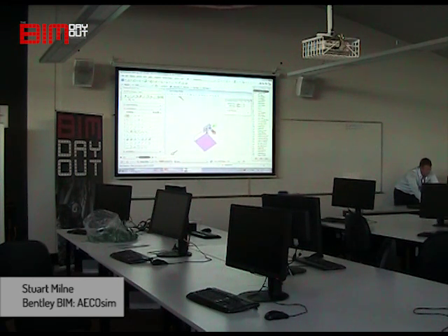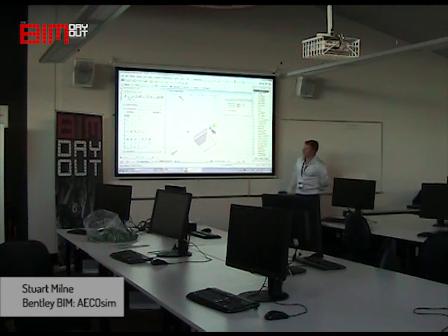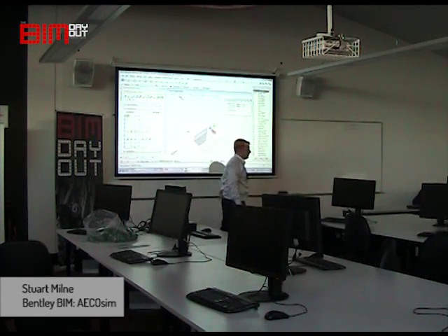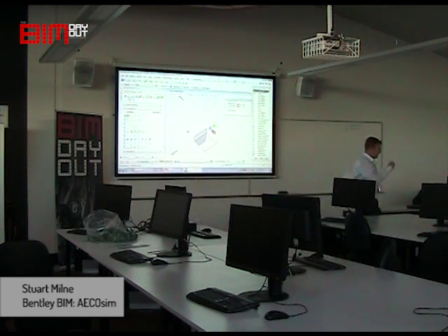Then we can use some existing points on the screen to snap to that point there. And we can finish the side of this up by putting that to the beginning. So there you go, you've got a plane there and a plane there. Using AccuDraw. How did everyone go on that one?